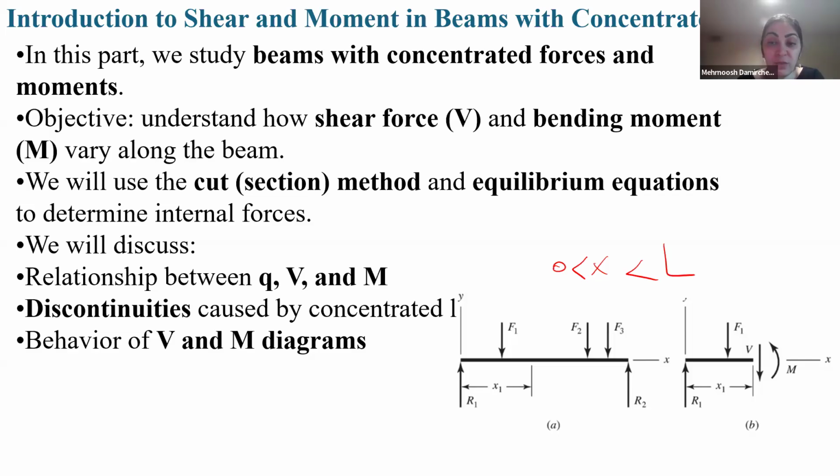We will use the cut method and apply equilibrium equations to determine the internal forces. Key points include the relationship between load, shear, and moment. Load means Q, shear is V, and M is the moment. And we talk about discontinuity and other things.